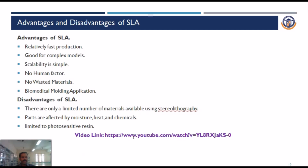Each and every process has some disadvantages. In the same line we have some disadvantages of SLA. There are only a limited number of materials available using stereolithography. Then parts are affected by moisture, heat and chemicals. Then limited photosensitive resins are used in stereolithography process. These are the disadvantages of stereolithography process.